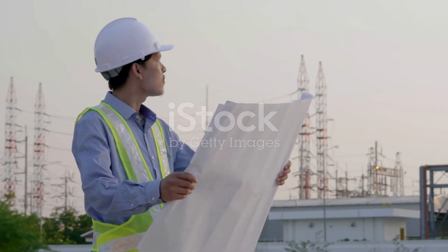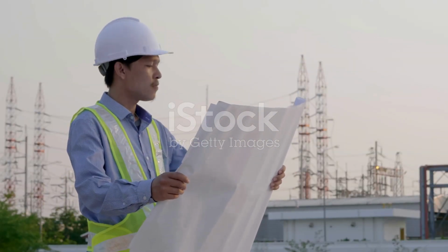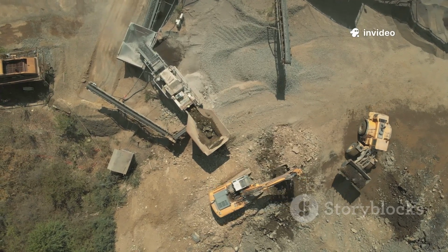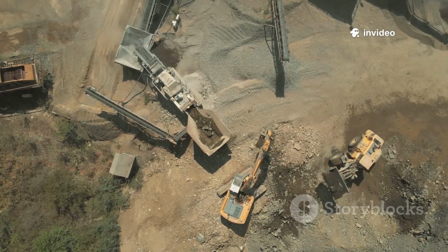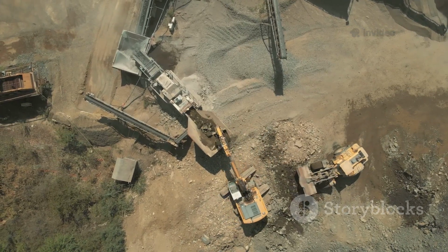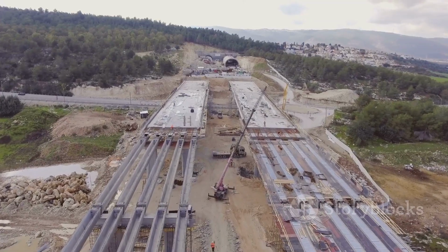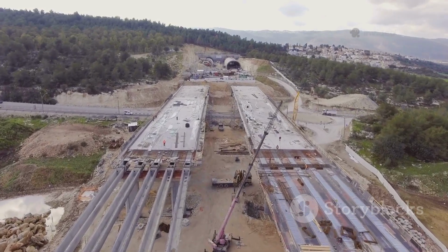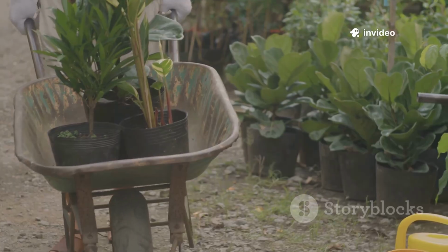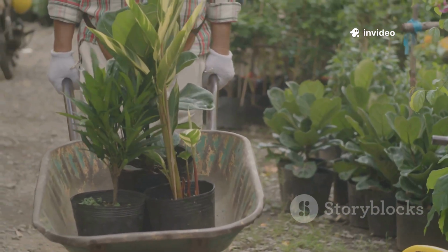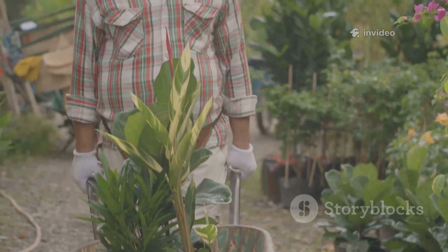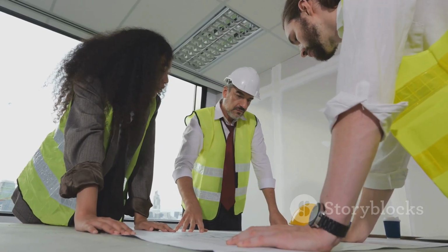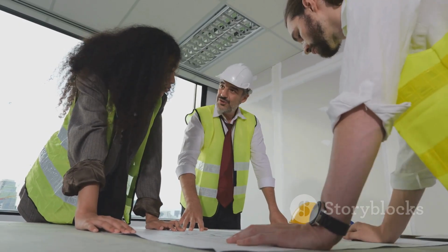Why is the mass haul diagram so important? In a word, money. Moving dirt is the biggest cost in road construction. Fuel, labor, equipment, it all adds up fast. The diagram helps minimize the distance every scoop of dirt travels, saving time and money. Think of it like digging up dirt for a garden. You take the shortest path, not haul it around the block. The mass haul diagram does this on a massive scale, planning the most economical haul routes before work begins.